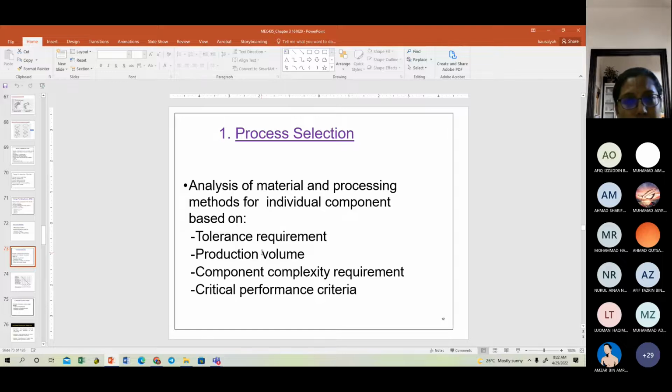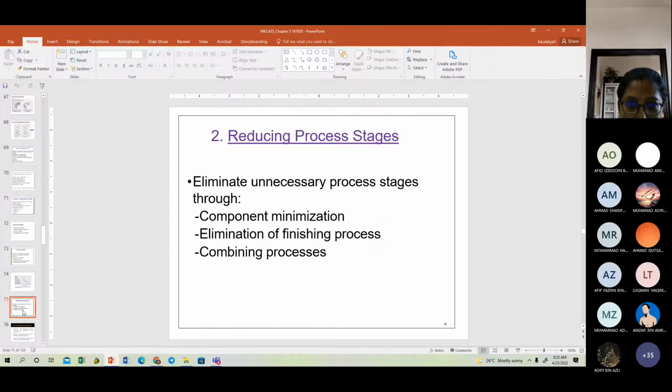But if you ask me and say, but madam, certain products can only be done through certain machining criteria. If that is the case, then in the step of design itself, you will have to understand there is a limitation. You cannot put in maybe too many fine, intricate details. Like if you have your engine, for instance, it's a casting process, right? So when it's a casting process, then we understand we cannot have very, very fine, intricate design features or profiles. So that is a limitation, and we understand that. And so when we are working on our CAD design, we cannot extend it in that direction, right? So these are all the factors which will help us choose our machining process, right?